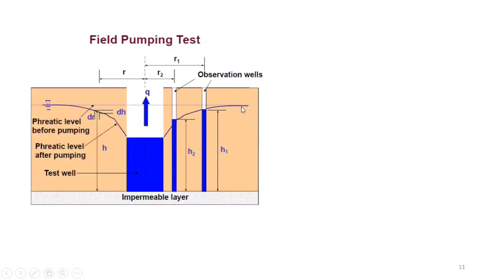In these tests, you are also looking for what we call the range of influence. Once you're pumping water and the water table is lowering, from the center, how much maximum distance will be affected or influenced, where you have some drawdown. In simple words, where drawdown becomes zero, from that point to the center of the well, it's called the zone of influence or range of influence sometimes.